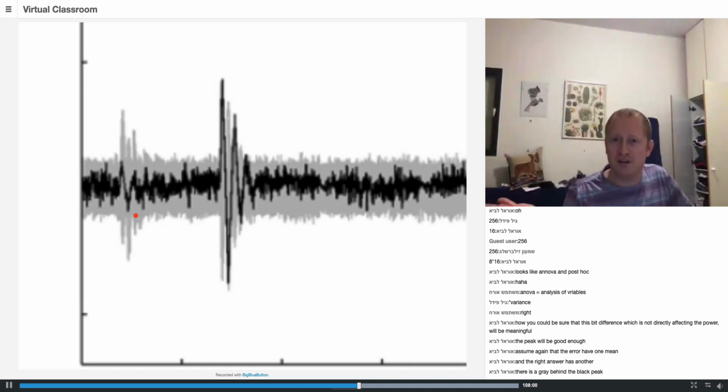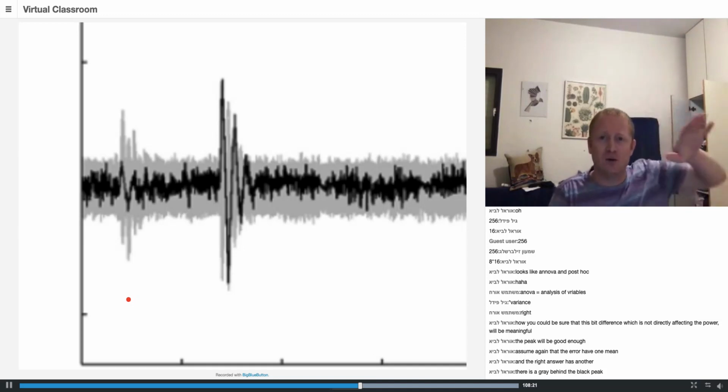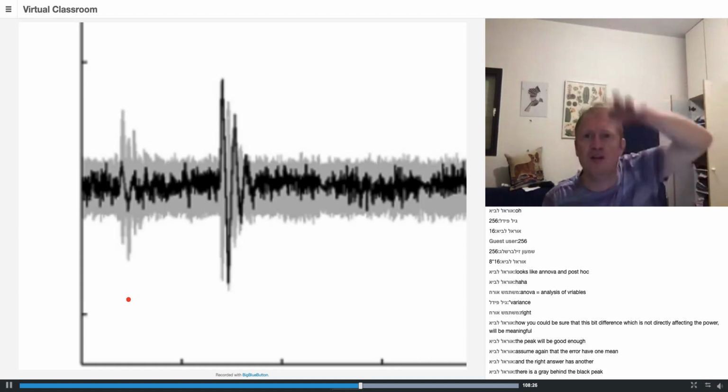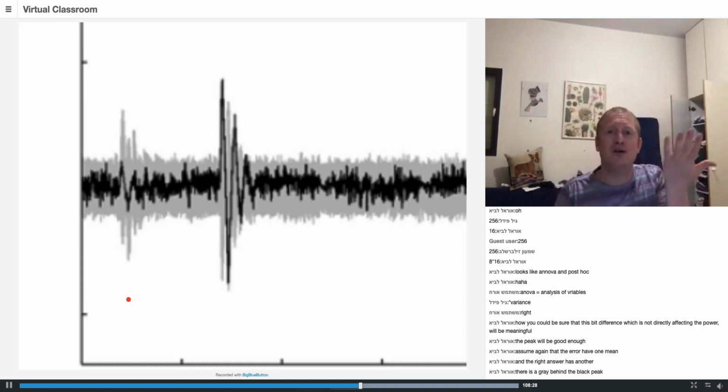What are we seeing here? Effectively, our power model wasn't very intelligent, and it looks like there was an incorrect guess which also got us a peak. This is called the ghost peak. Why is this? One possibility is that we were actually looking at the inverse of our guess. So, you know, when we're using a microcontroller, first the bytes are loaded in, and then they're loaded out. So you're also getting the complete inverse. You're also getting peaks on that.